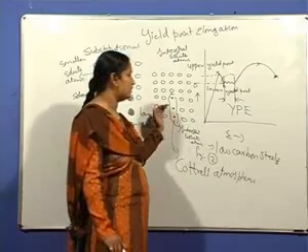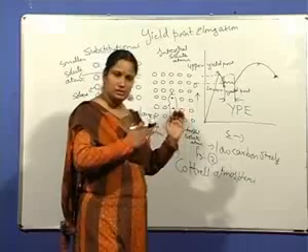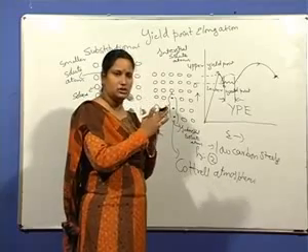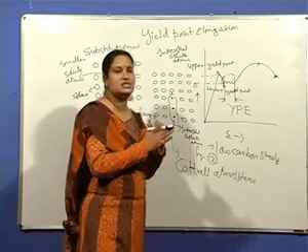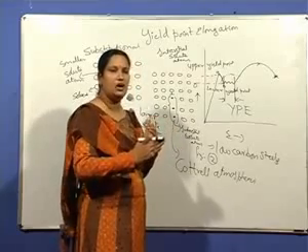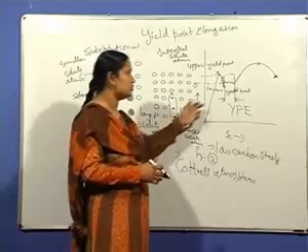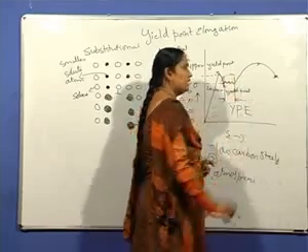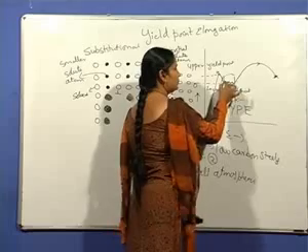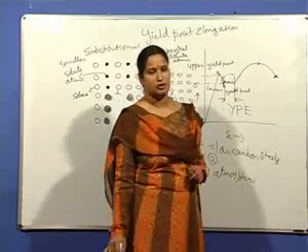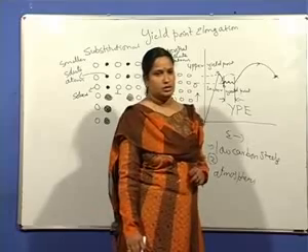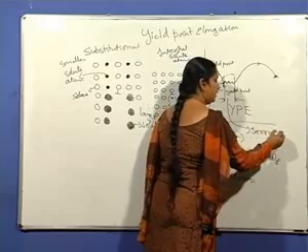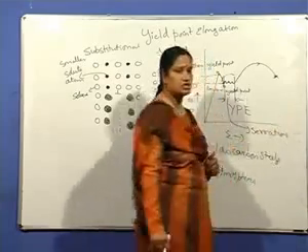Moreover, once the dislocations are torn away from these atmospheres, the plastic deformation continues. Again, if they are unlocked, again the dislocations are locked by these atmospheres. More stress is required to deform. Unlocking of the dislocations from these atmospheres gives rise to this lower yield point. That means this serrated region. This zigzag portion is known as the serrated portion of the stress strain curve. So this creates serrations in the stress strain curve. S-E-R-R-A-T-I-O-N-S. This is known as serrations.